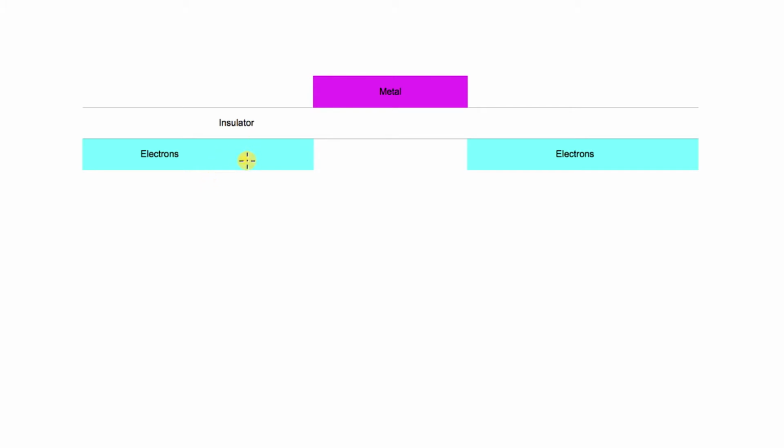So electrons are much happier staying in this region than going off into the silicon where there aren't any of those positive charges. That means that to try to get an electron to go from this region where it's happy along with its atoms that brought it there, out into the silicon region that doesn't have those donor atoms, is going to take energy.